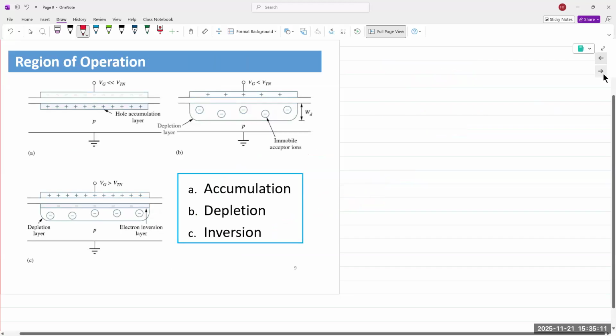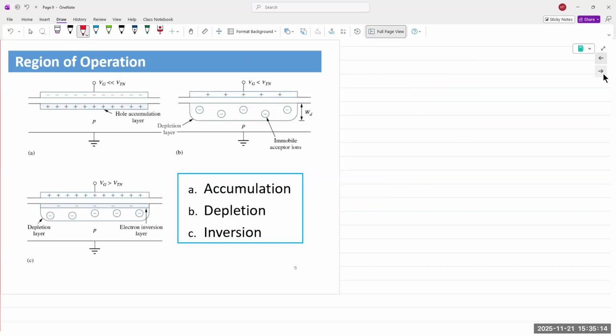All right, so let's look at how and why these are very popular. MOS technology has been the de facto standard technology for pretty much all major microchips for the last several decades. One of the reasons is very low power consumption in the off state. In a standby state, standard BJTs or diodes or other components, resistors for instance, use electrical energy or power at idle. MOSFETs consume very little to no energy.